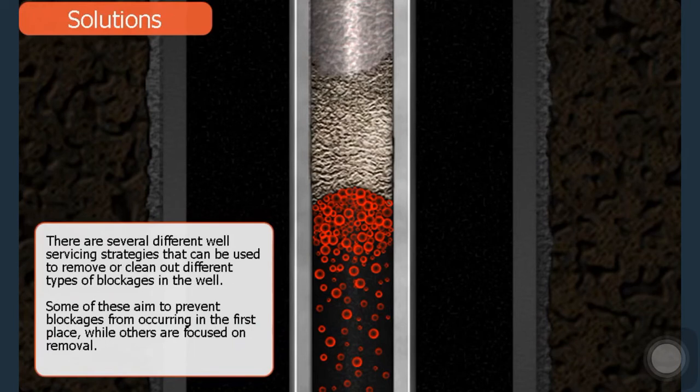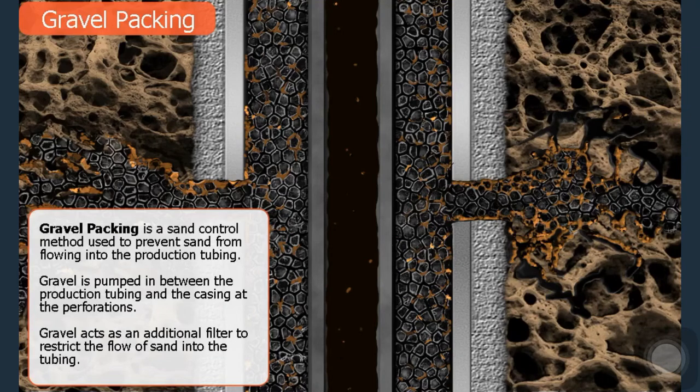There are several different well servicing strategies that can be used to remove or clean out different types of blockages in the well. Some of these aim to prevent blockages from occurring in the first place, while others are focused on removal. Gravel packing is a sand control method used to prevent sand from flowing into the production tubing. Gravel is pumped in between the production tubing and the casing of the perforations. Gravel acts as an additional filter to restrict the flow of sand into the tubing.